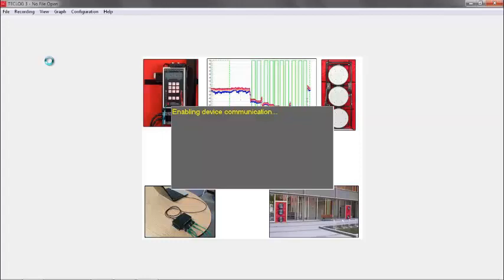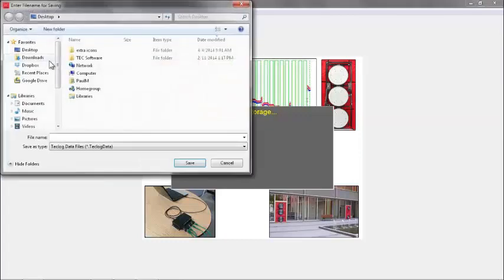So again, we're testing 2 units, and we're only using 2 outdoor references, one for each fan. So we're setting up similar to just running 2 single fan blower door tests. We'll give this a name. We'll call it Test AB. Save that to our desktop.